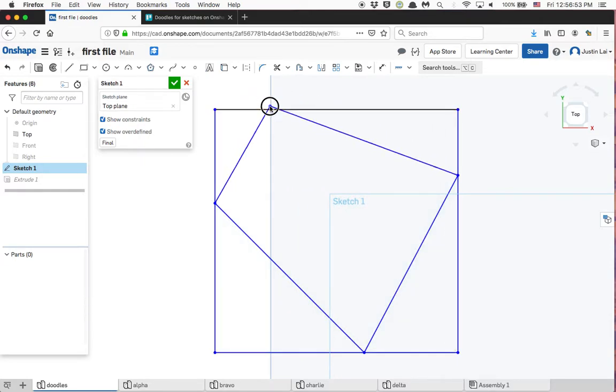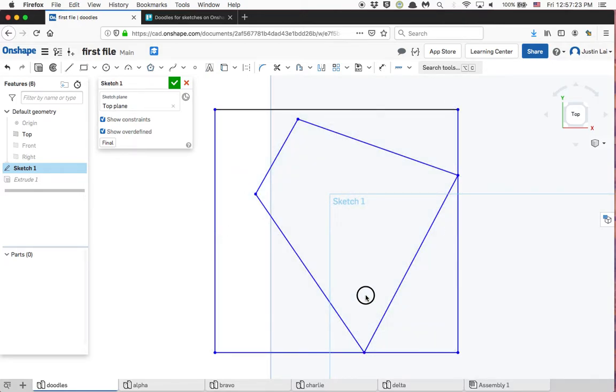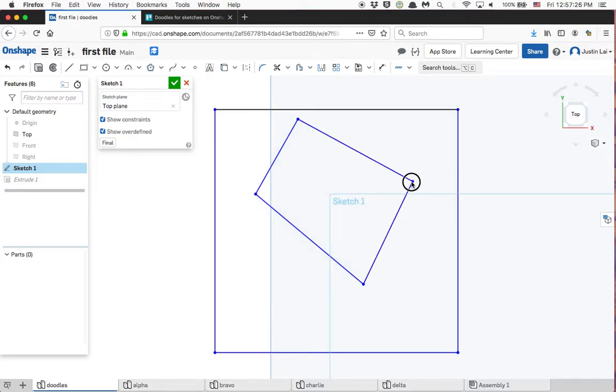Oh, good. Yeah, so that makes sense, right? Our shape is still maintained, but we can freely move it above and below that top edge, and Onshape is like, hey, you want to make it coincident again? All right, so let's free that and just go around and delete these pieces. Go around and make sure. Oops. Let's see, give it a try. All right, look, our shape is free. Did I do this one? I did. And then if you want, you can further deconstruct it.